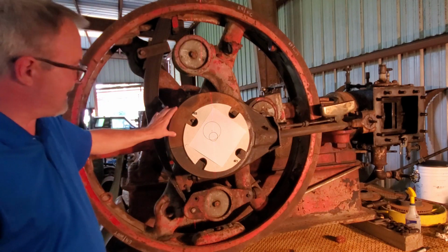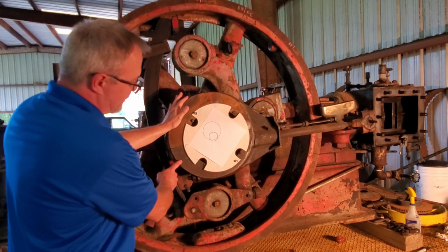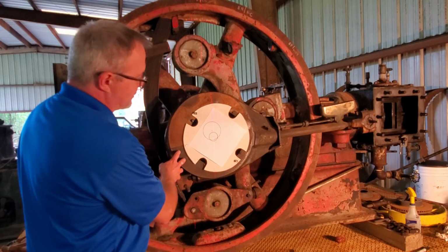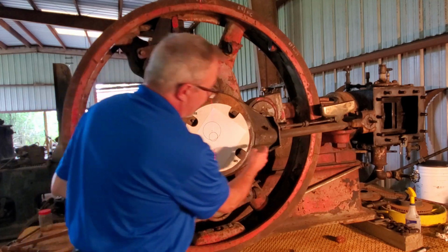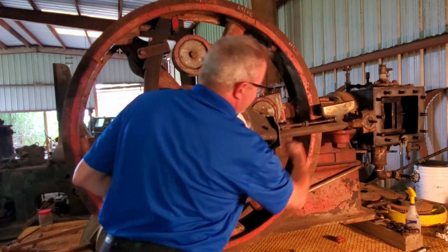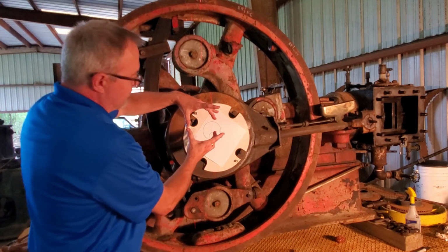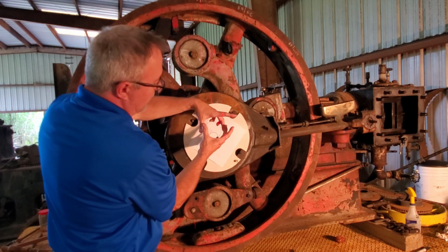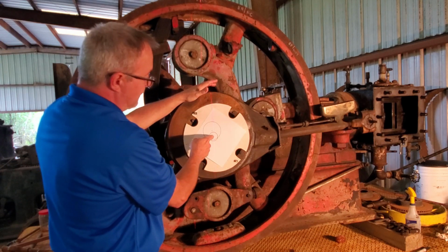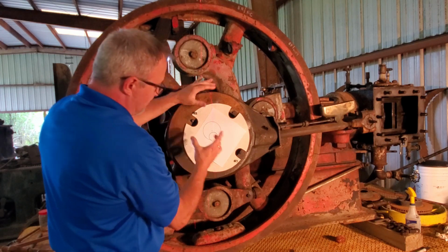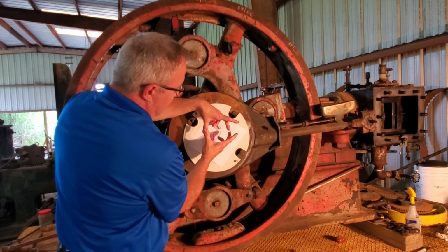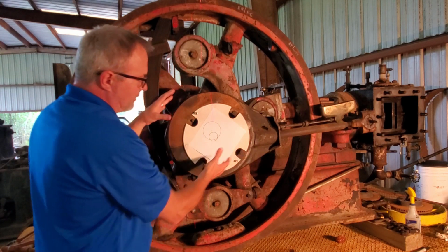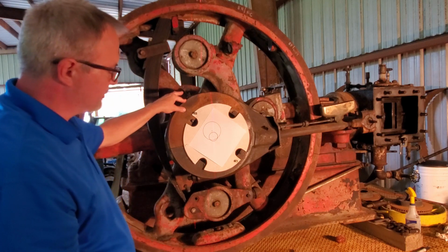So I have an idea where I think I'd like to re-engineer this. I'm going to make a reversible change to this engine and replace this end of the eccentric rod, and it unbolts here. So I can use everything from that point forward, but use a modern spherical roller bearing, and all I have to do is make an offset holder to hold that spherical roller bearing in the correct place, and I won't change any of the timing events, but it'll just be much smaller. It'll do the same job. It won't have the issues with play and having to possibly re-babbit this surface.